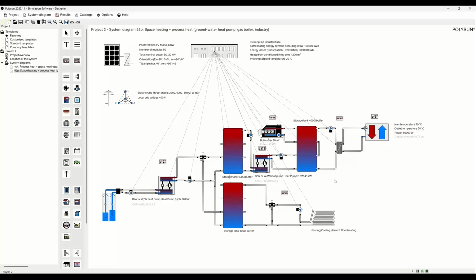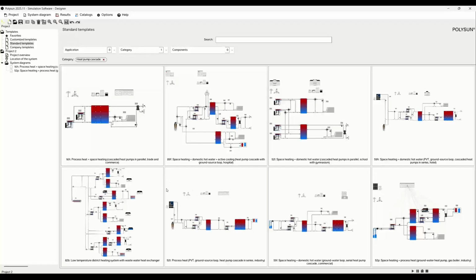sink here. Then also, and this is already a look into the third system, or it's not a new type, it's basically a mix. So there are also hybrid systems. Here there's a hybrid system because we have a gas boiler that actually helps to get up the temperature to a certain level. And of course, we can also mix heat pumps in series and heat pumps in parallel. And then I can show you the Cascade heat pump schematic diagram also for an example of a hybrid system.